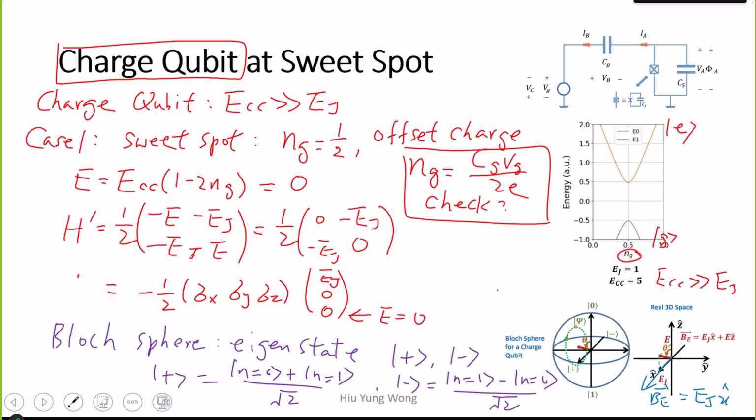So it is very sensitive to charge noise, because this is an intended capacitor, but your system is also coupled to the environment through other capacitors. You cannot ignore or avoid that. There is always capacitive coupling to the outside world on a chip, right? So if you have different charge, then this is called charge noise. It means you are very sensitive to charge noise.